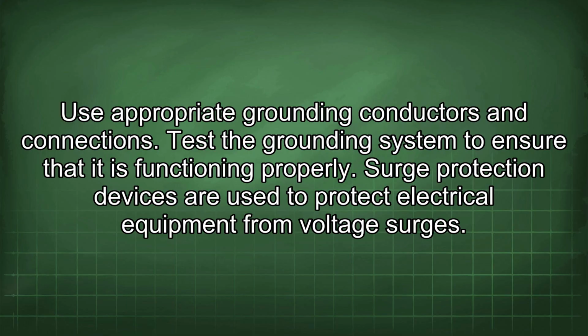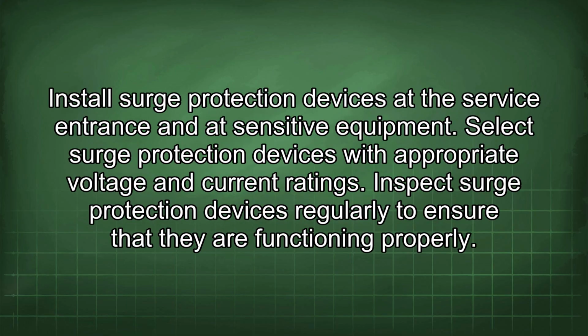Surge protection devices are used to protect electrical equipment from voltage surges. Install surge protection devices at the service entrance and at sensitive equipment. Select surge protection devices with appropriate voltage and current ratings. Inspect surge protection devices regularly to ensure that they are functioning properly.